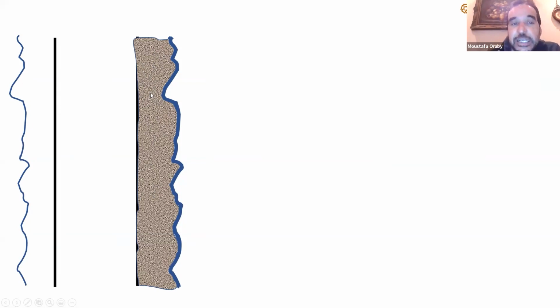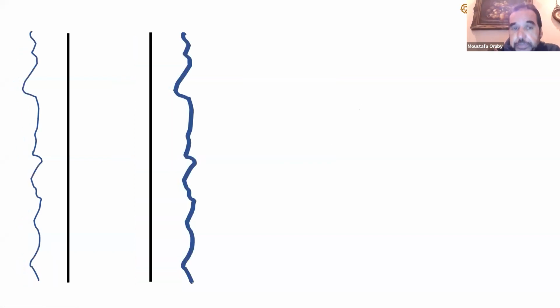I'm just taking this as an example. So the cement here is between the casing and the formation. We call this an excellent cement job. The bonding is good. The cement is filling the space, or the annulus, and this is an excellent job. No trouble here. This is what we all like to have in every well.